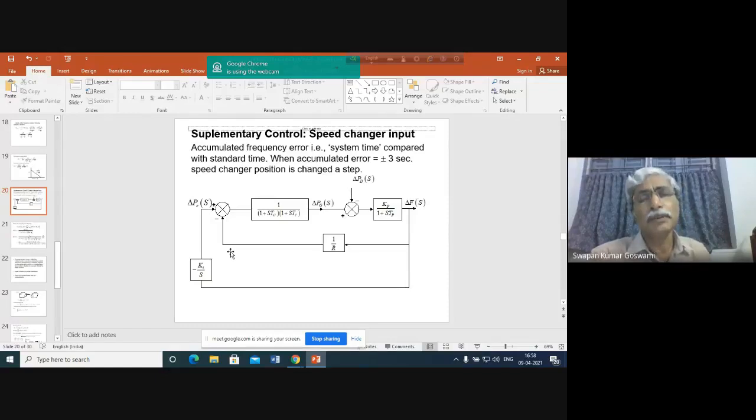Obviously, a given power output may be obtained from a number of generators in many different ways. Many different combinations of power output may be achieved for a number of generators working in a power system. So we shall be operating the generators in such a way that the total cost of operation becomes minimum. Operating the generators in this way is called solving the problem of economic dispatch, generating or dispatching power in the most economical way.